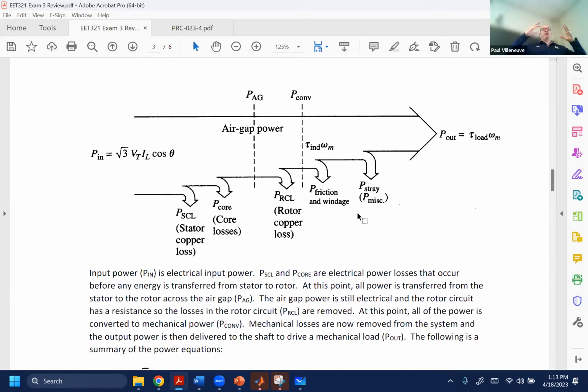A better example is riding a bicycle, pedaling as fast as you can in your tuck position. At some point, you just can't pedal any faster. That's because your applied torque, you're pedaling your butt off, and the wind resistance plus the road resistance are the same. When you reach torque balance, you don't continue to increase in speed. That's why it's induced torque: it has to cancel out your applied torque. Otherwise, you haven't reached a stable operating point, and your speed continues to increase.